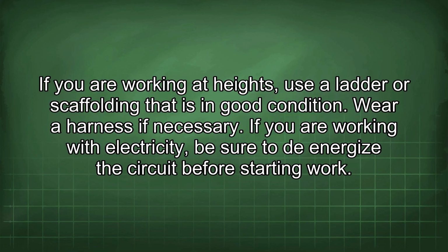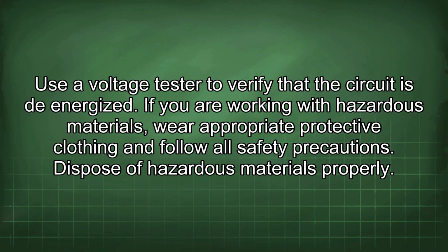If you are working with electricity, be sure to de-energize the circuit before starting work. Use a voltage tester to verify that the circuit is de-energized. If you are working with hazardous materials, wear appropriate protective clothing and follow all safety precautions. Dispose of hazardous materials properly.